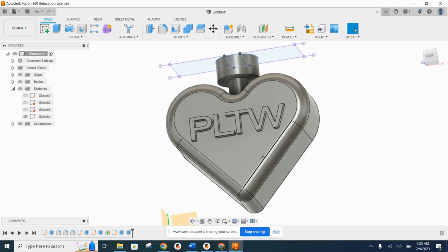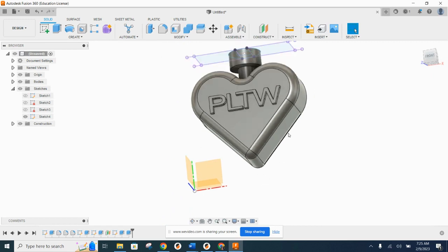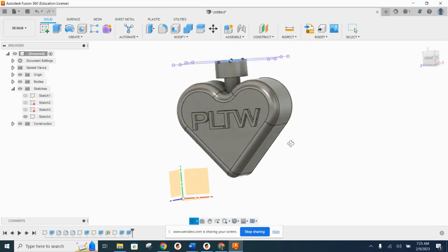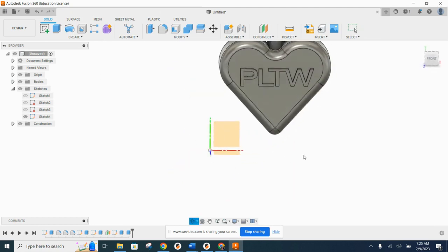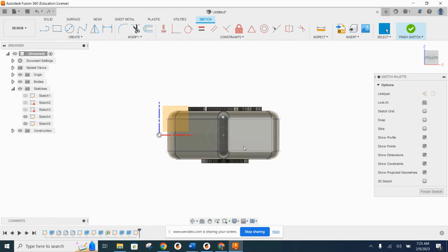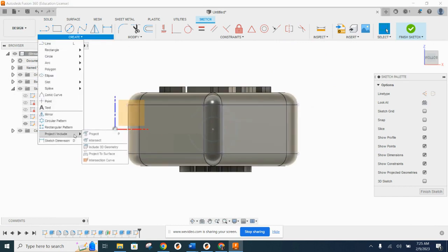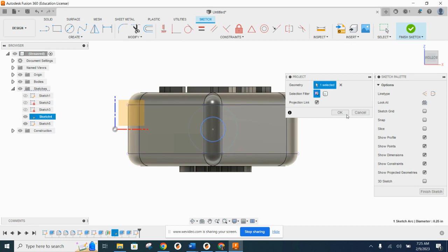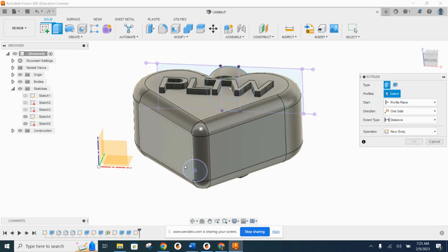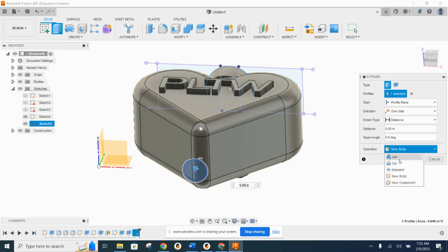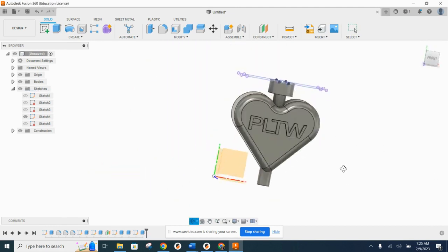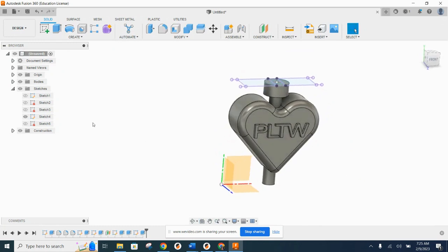And as I said before, we also need to make sure that there's going to be a vent at the bottom so that material can actually escape. Okay, so I can see that this work plane here is well below the candy. So I can create a sketch on this. And now, this is kind of clever, we can project that circle that I've already created forward. And now I can just finish the sketch. This is when I can use extrude as a join, and I can send this all the way into that chocolate. Okay, so that's really what we need.